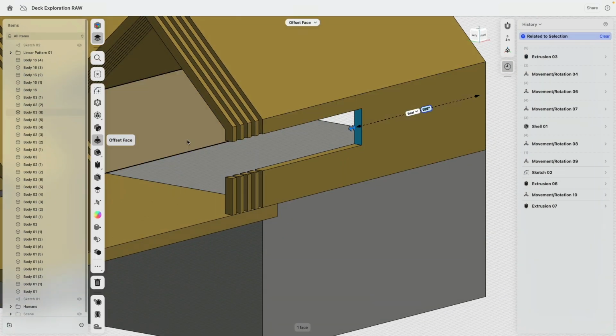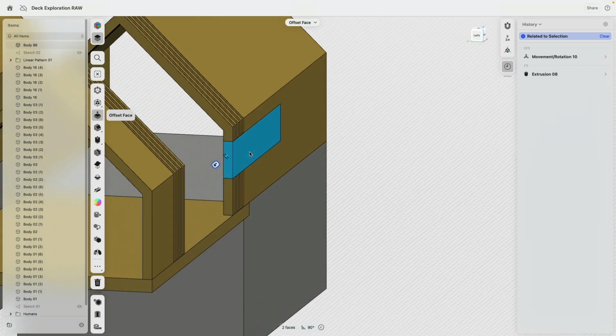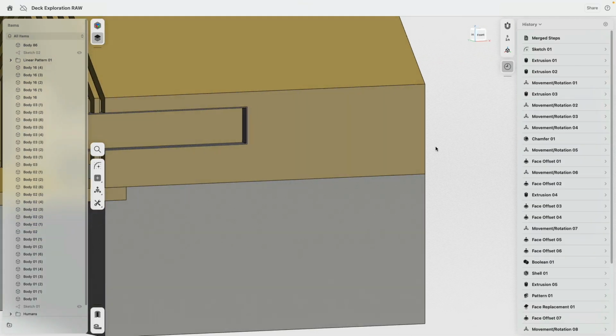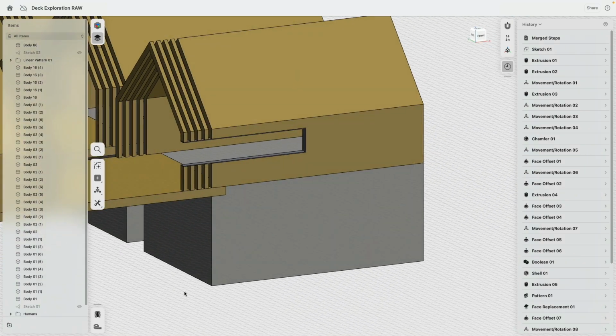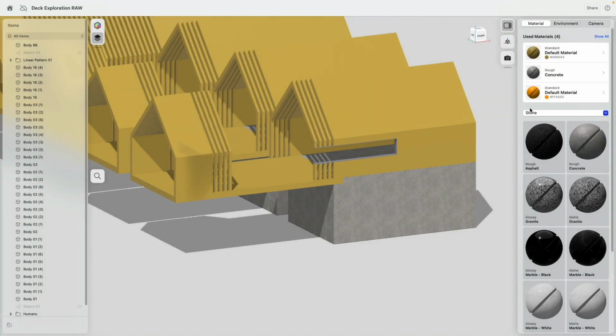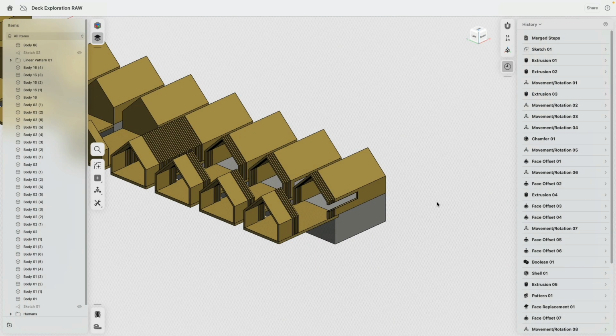So we can do the following. We select this one more time. We do an extrude. I extrude to this face as a new body. Very good. Then I select these three faces. And then I do a shell, and let's say 1 inch of a material thickness. And there, bonk, there is actually the piece that fills it. No? Easy peasy. Then we can go to the visualization command and add this one more time to there. Perfect. Beautiful. No?